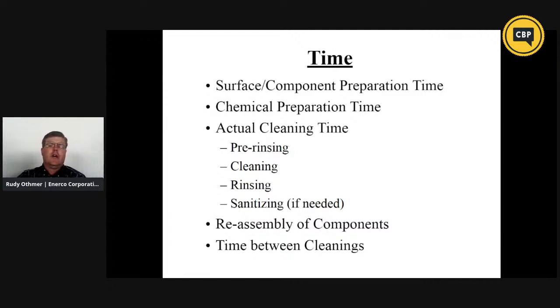You've got mixing time to get your acid CIP in there, and then the 15 minutes begins. So time is an important component in thinking about and designing a full system for cleaning.